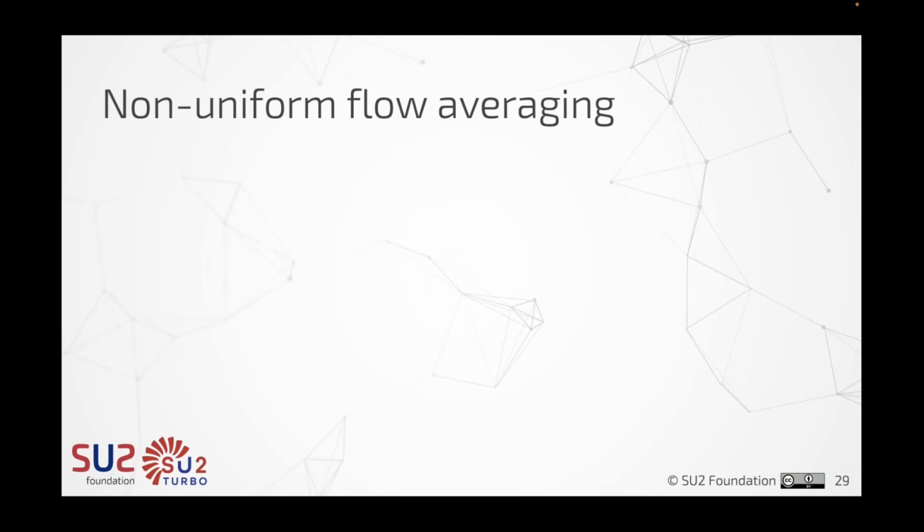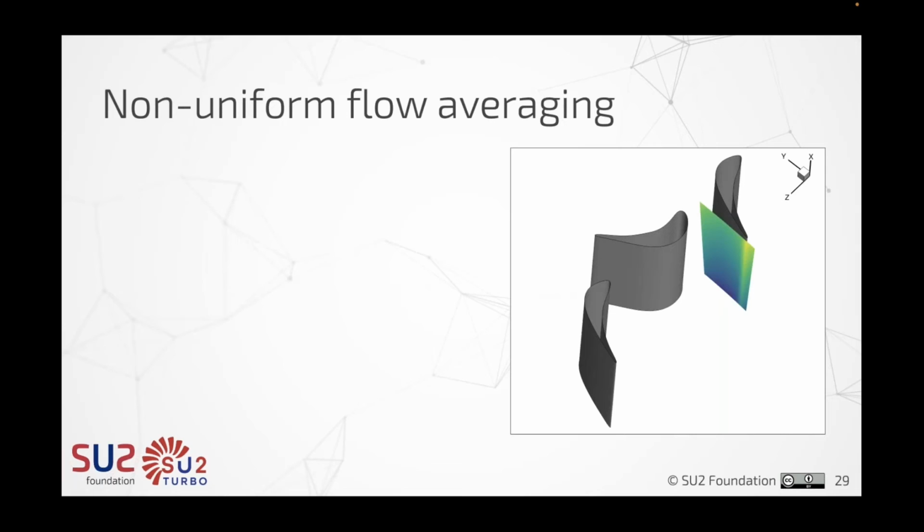All right, so it's quite common in a turbomachinery application to encounter non-uniform flow. As an example, here you see the surface behind the first stator. Here it was static pressure, the quantity that was plotted. And as you can see, this is quite non-uniform, both spanwise, that is from lower to higher radius, and also in the pitchwise direction, that is along this tangential direction.